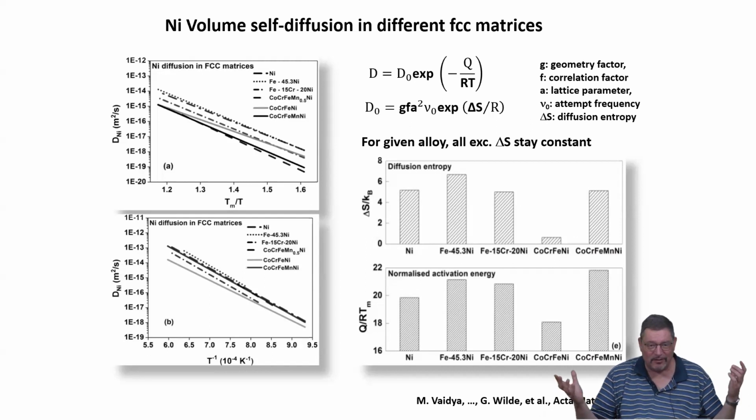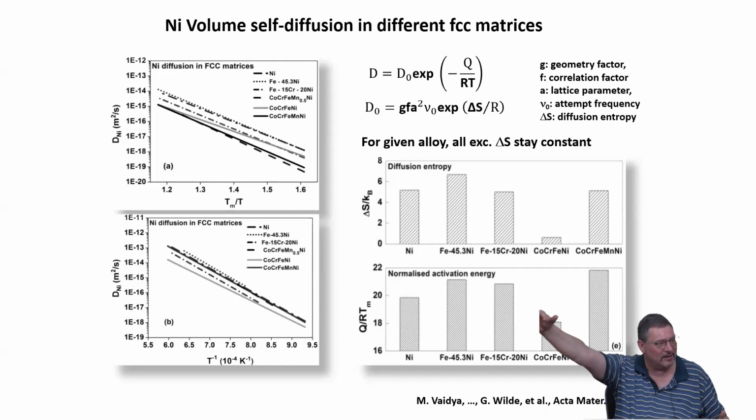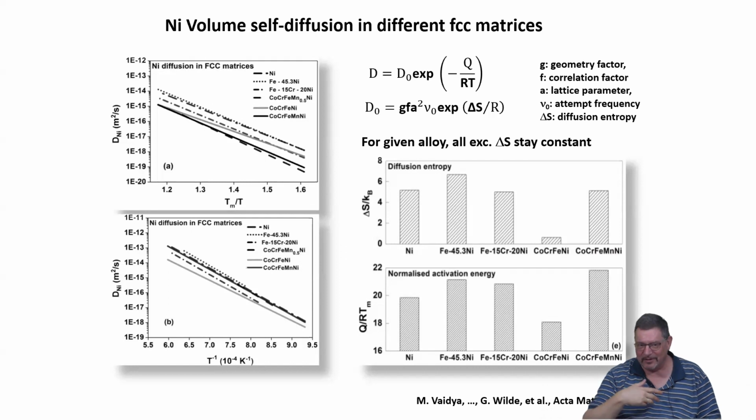If you see, oh, well, great, the yield strength is maintained up to much higher temperatures. Wow, the grain size may stay small up to higher temperatures. All these effects which we really need to create all this nanostructured materials business, which has been going on for, I don't know, 30 years or so, was always limited by, for example, having grain growth occurring at much too low temperatures. So having materials which are stable is fantastic for many, many aspects. But how to explain this if diffusion is not sluggish?